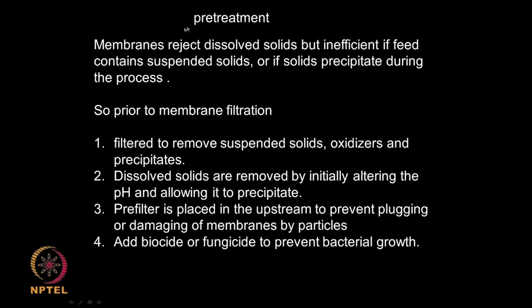If you have dissolved solids there is no problem, but suspended solids, or solids that precipitate during the process, are a problem. So, prior to membrane filtration, we can have another filter to remove suspended solids, oxidizers and precipitates. We can initially adjust the pH so that dissolved solids precipitate out, and then have a settling tank or filtration, and then a pre-filter to prevent plugging. Then we can add biocides or fungicide to prevent bacterial growth.